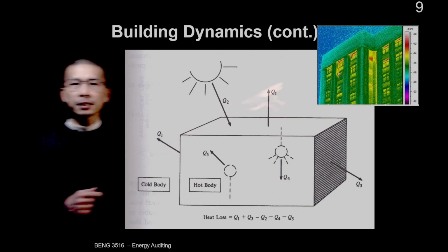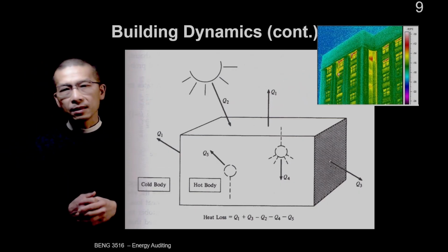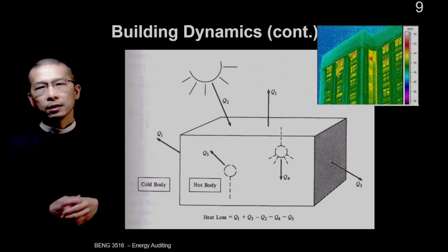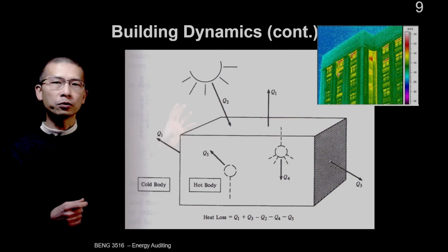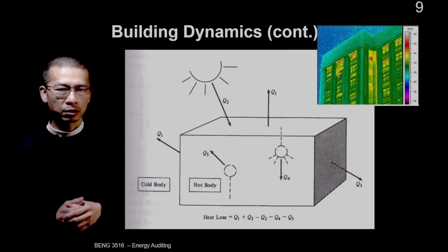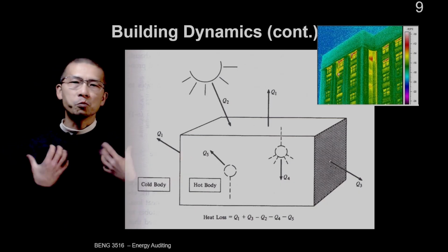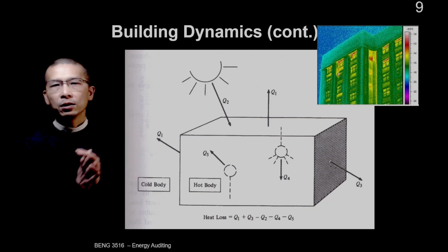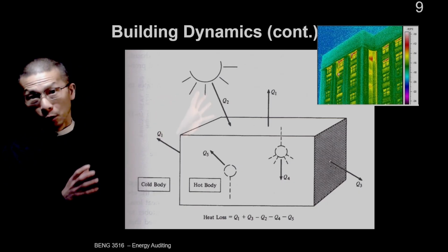Can you see this infrared thermography? It's in the context of the building envelope. This is one of your most powerful visual tools for showing invisible energy loss to a client, right? We use this infrared camera to see what our eye cannot see, because it's thermal radiation, right?